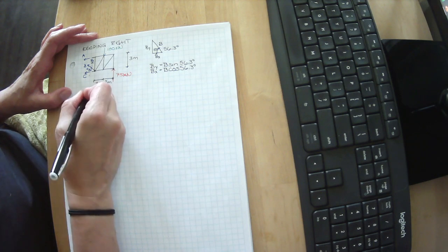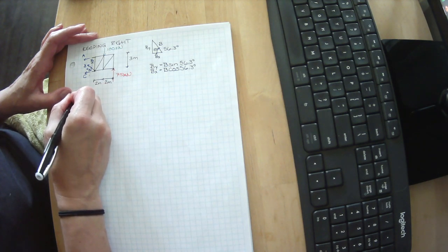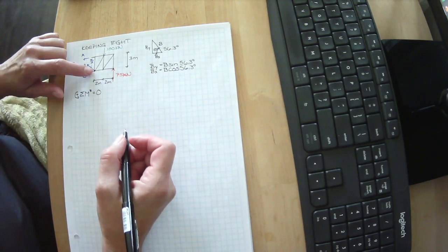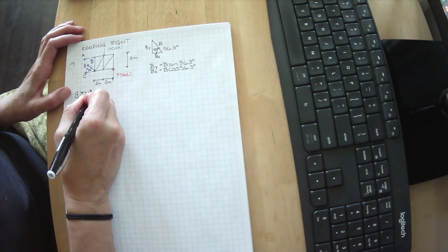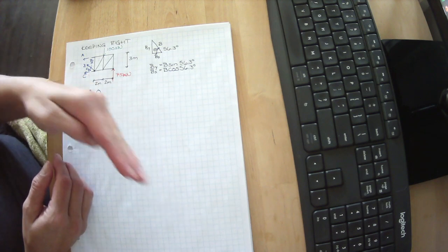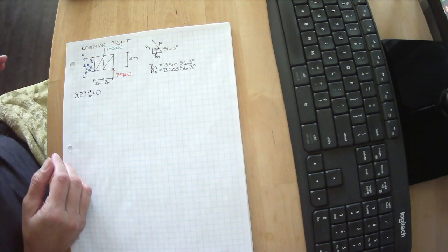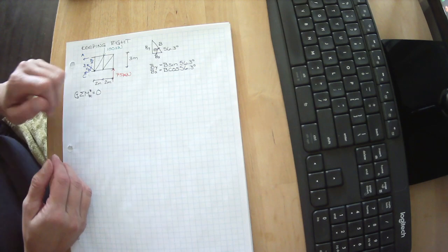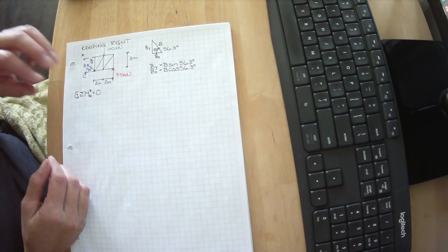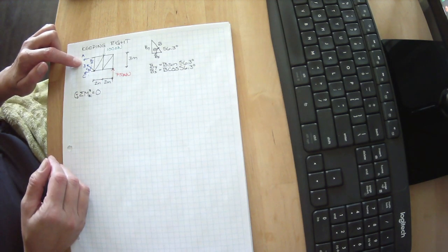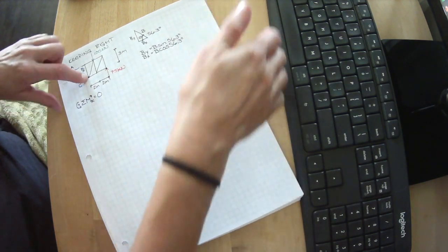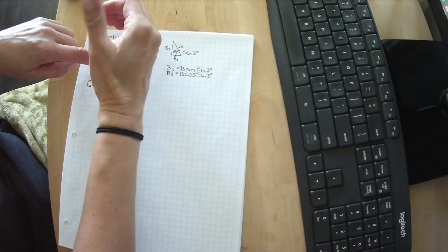So I'm going to sum the moments about the z-axis, where everything in that direction is positive, and I want to know what it takes for this to be in static equilibrium. And I'm going to pick this node, BC. So I'm going to put my thumbtack right here. B passes through the node, which means By and Bx do. C passes through the node. That's great. That gets rid of 3 unknowns that were going to plague me. It leaves me only with an unknown of A. So I put my thumbtack here. A is trying to spin my paper in that direction. Curl my fingers in that direction.